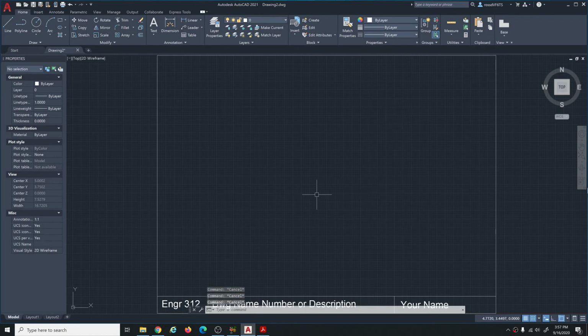All right. Then draw line somewhere. F8 ortho will help you keep these horizontal up to there and then up to there. Then offset. Best command in the world, offset. This thing is 3 inches wide, so I'm gonna offset 3 inches, and then I'm gonna offset 1 inch.